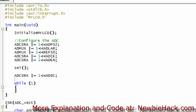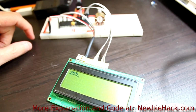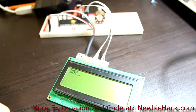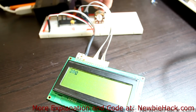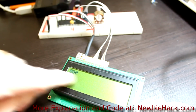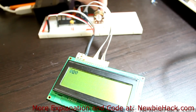REFS0. Okay, so let's go ahead and make and program and see what we have. The microcontroller has been programmed, and we can see that there is a 255 on the LCD screen. If I turn the potentiometer, the number will be going down. But notice that there is a leading 0 here, which is undesirable.